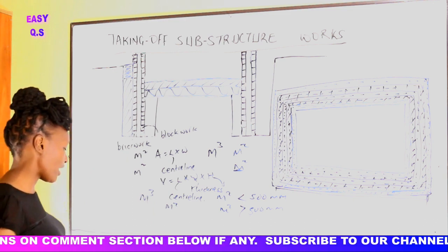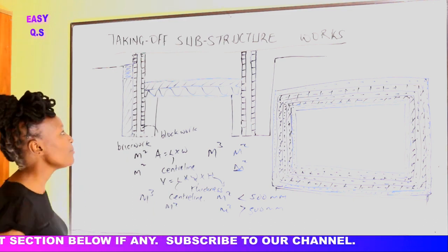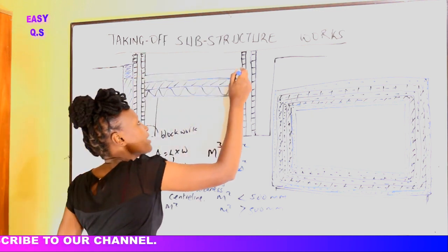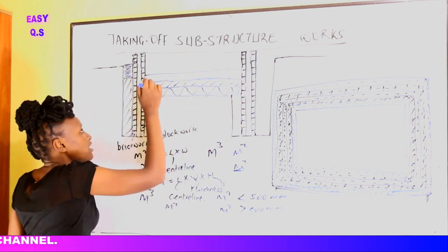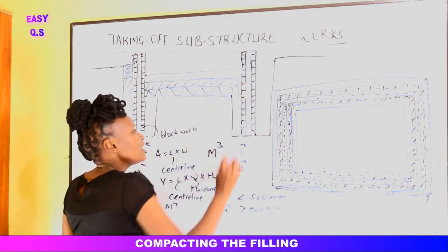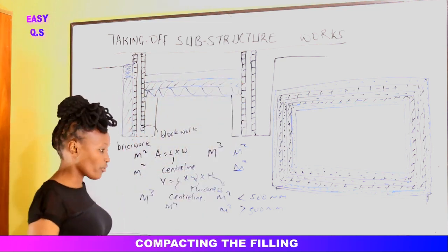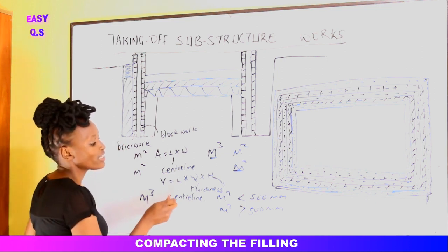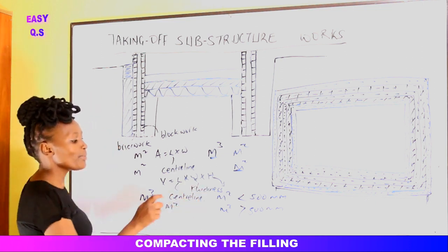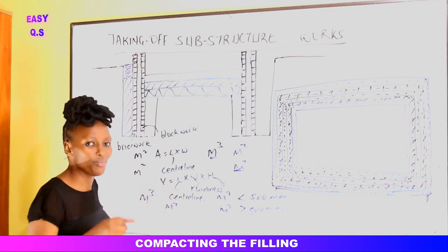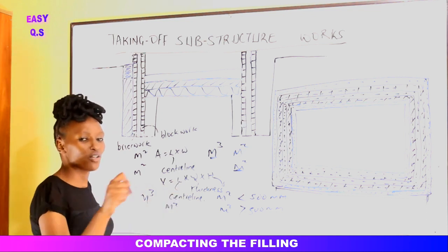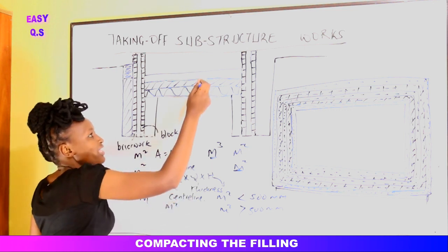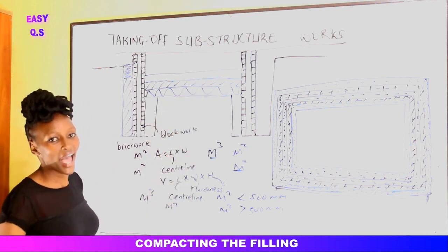Alright, the same area. So we shall go to the concrete bed, because on top of the insulation bed, we shall come and lay our concrete bed now, the floor, the concrete. If this is our concrete bed, we are told that we should measure it in terms of meter cubed. If it's measured in meters cubed, it is length times width times height. So the same area, length times width, inside the building, the same dimensions, internal dimensions of the house, length times width. Then we shall multiply by the thickness of the concrete as the height.